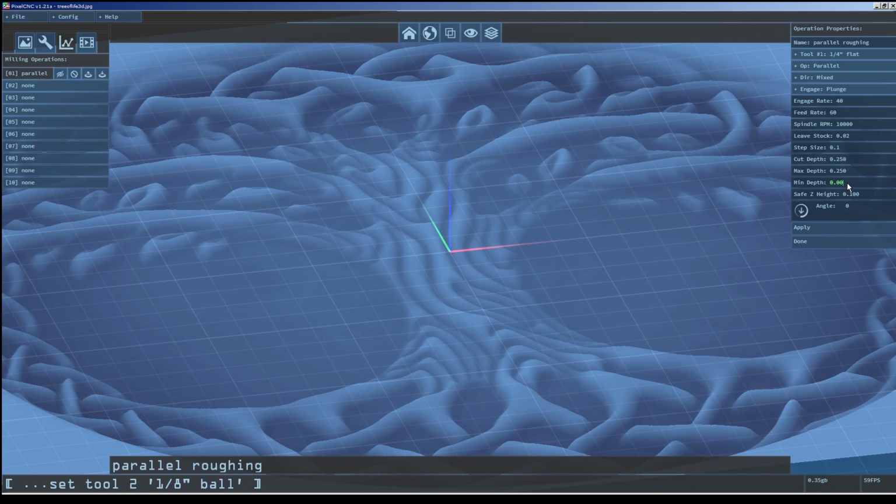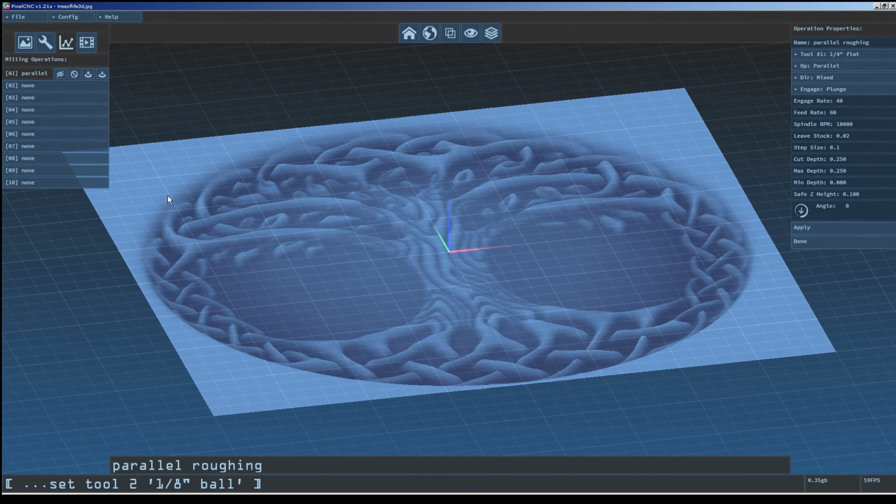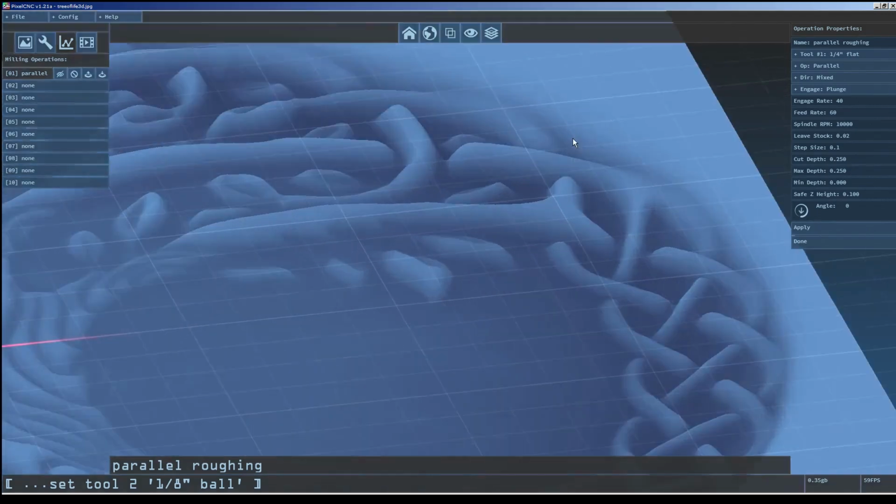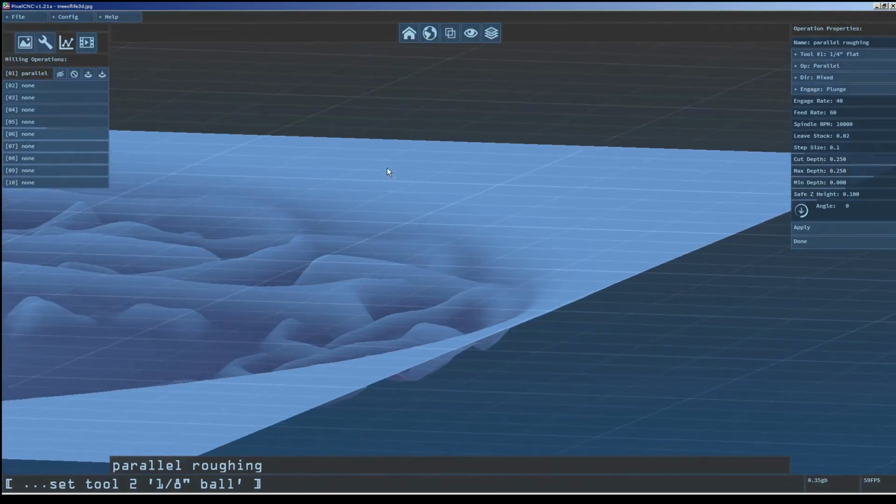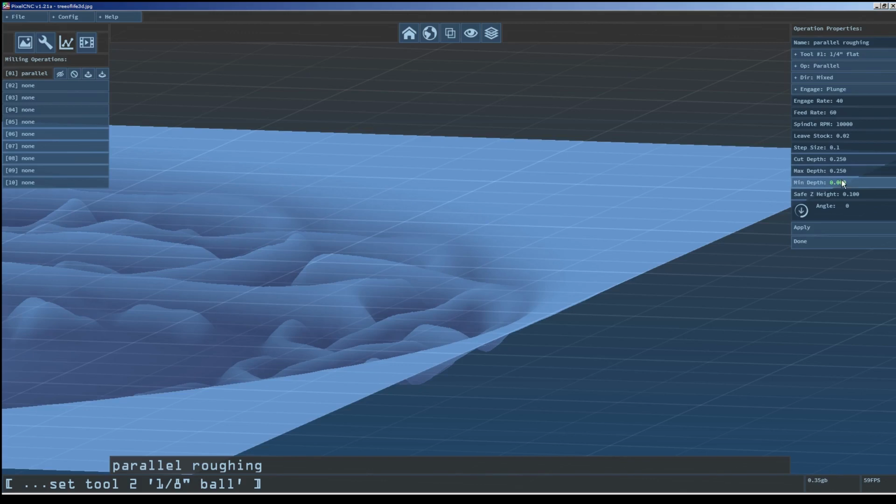Shallow cuts that might skim the top surface can be undesirable with a workpiece that may be stained or painted, for example, or that otherwise has an irregular or uneven surface that's not level with the CNC. Preventing shallow cuts is also useful if the input image has a soft or fuzzy boundary between its topmost surface and areas to be cut. This happens to be the case with our tree of life image, specifically its outer edge, which smoothly transitions into the pattern of weaved roots and branches. For this project we will use a minimum cut depth of 30,000ths, or 0.03.